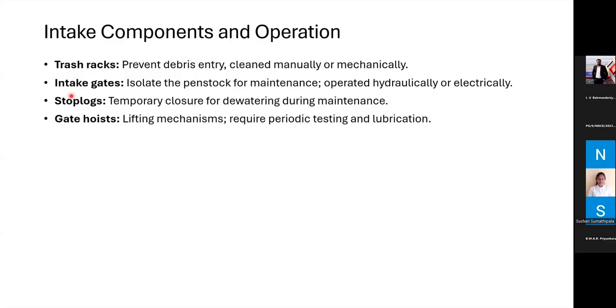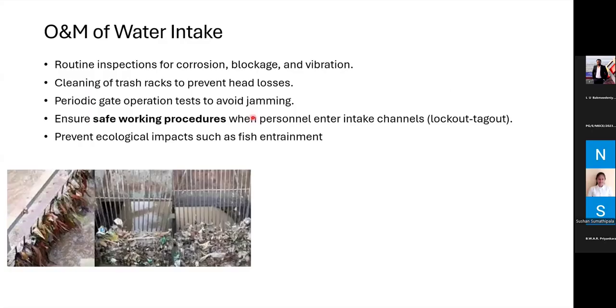At that state, you will not have a means to temporarily close the water into the tunnel. Then you will have to create a dewatered area by building a dam across the tunnel intake, and it will be a really expensive job to carry out. So basically, these elements in the water intake that are not used much need to be properly tested and maintained for the proper operation of the power station.